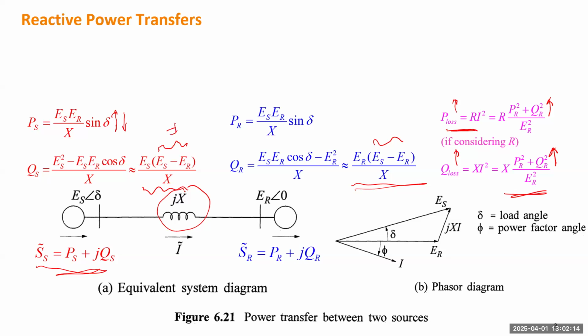So this can never be zero, right? You will have a difference of voltages between any two neighboring substations. So if you want to deliver reactive power from one point to another, you will intentionally create such a voltage gradient to determine where the power flow will go.